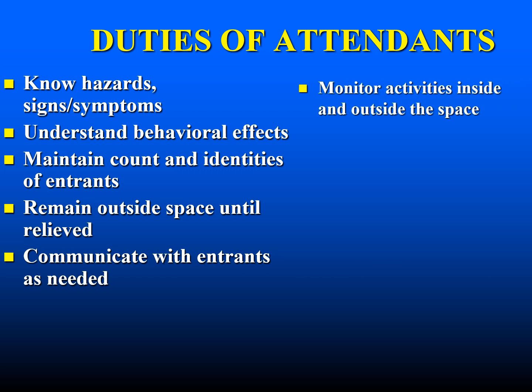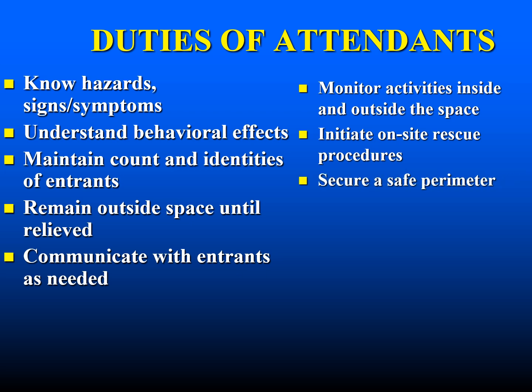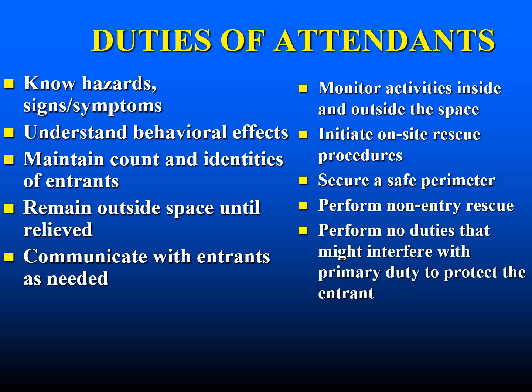They must perform monitoring activities inside and outside the space, initiate on-site rescue procedures, and secure a safe perimeter. These are all duties of attendants. They perform non-entry rescue as well, and perform no duties that might interfere with the primary duty to protect the entrant.